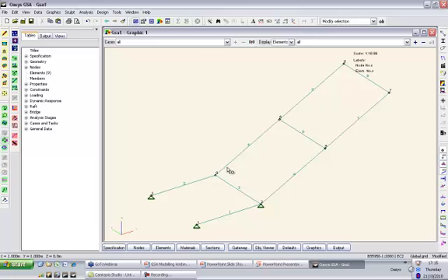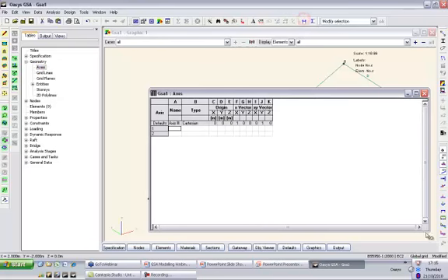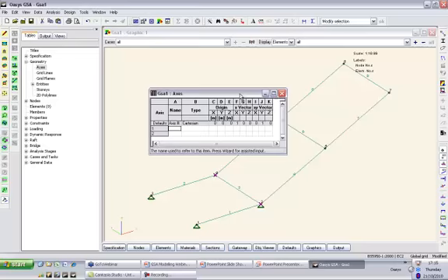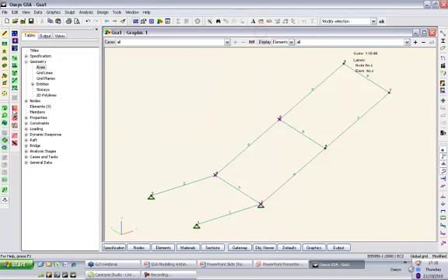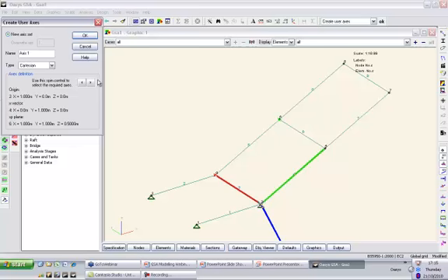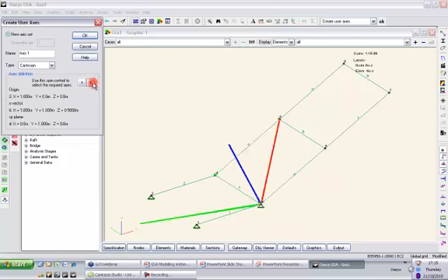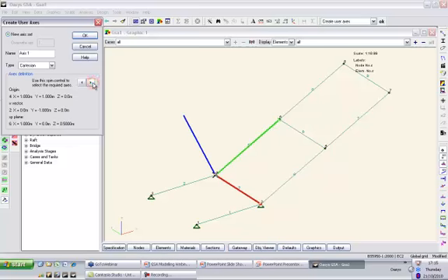People sometimes ask about axes. Now this is a sloping member. If I select those 3 nodes, I can create an axis directly by typing into this table. Note the use of the size columns to fit. Very useful command. Alternatively, I can use the create user axis command, and what this does is we can toggle through the various options of those 3 nodes until I get to the axis set that I like.